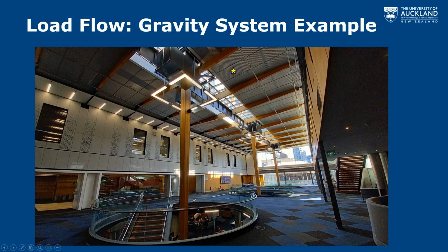Well, if we're a yellow star, we've got this big open glass bit and can't really get any load in through here. And for a load path, it's sort of like electricity. It wants to take the lowest energy path that it can to get to a reaction, just like electricity wants to take the shortest path, the lowest energy path, to discharge to ground. Again, a very similar analogy here with structures.